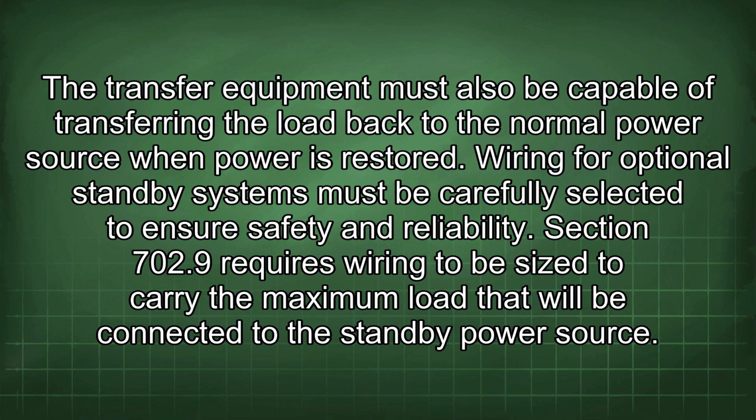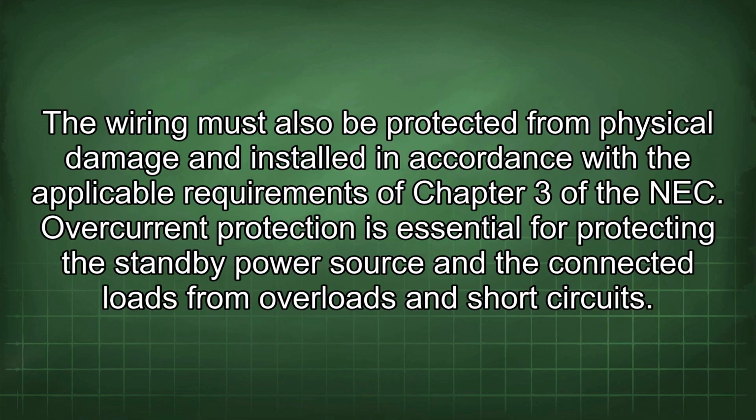Section 702.9 requires wiring to be sized to carry the maximum load that will be connected to the standby power source. The wiring must also be protected from physical damage and installed in accordance with the applicable requirements of Chapter 3 of the NEC.